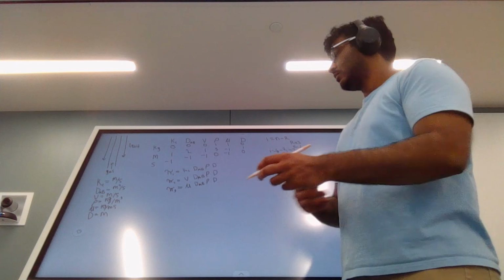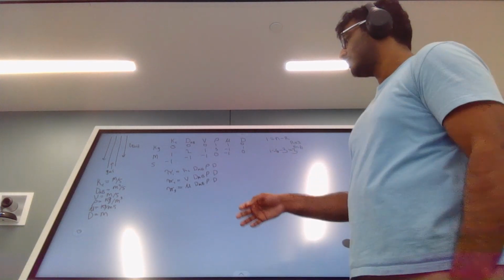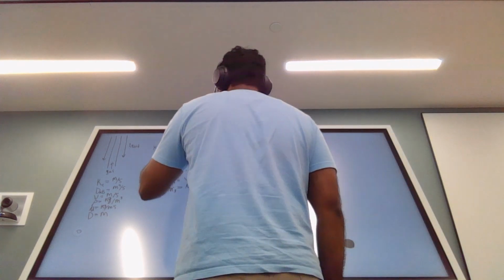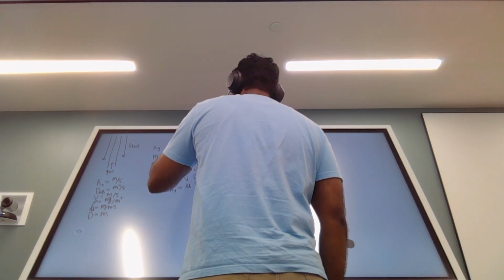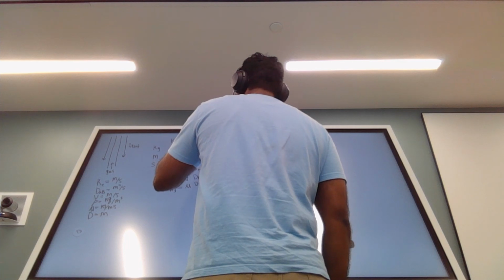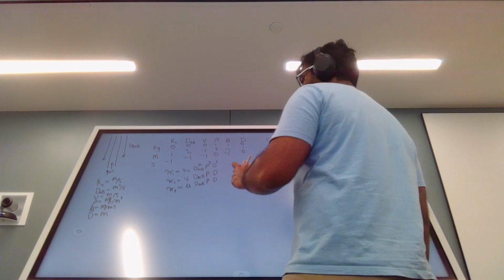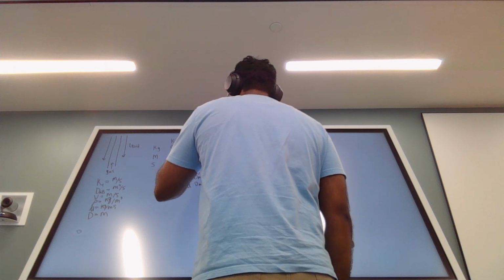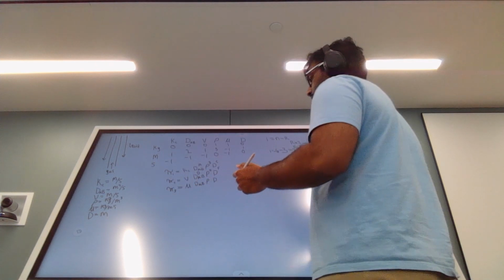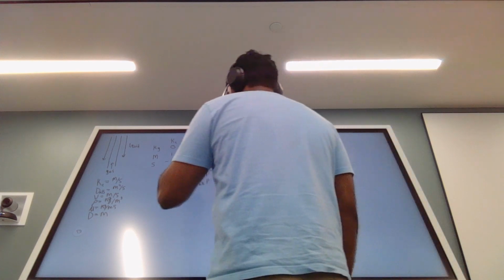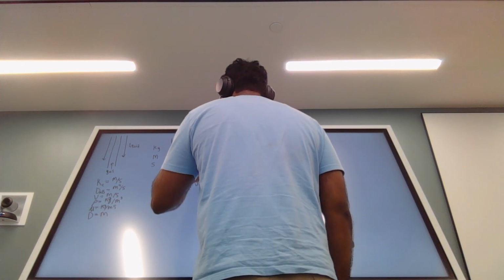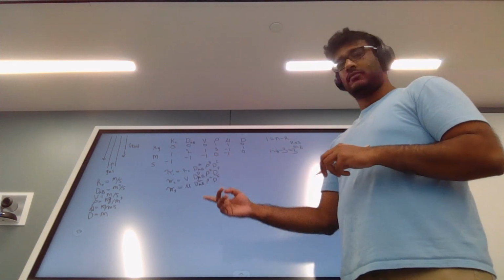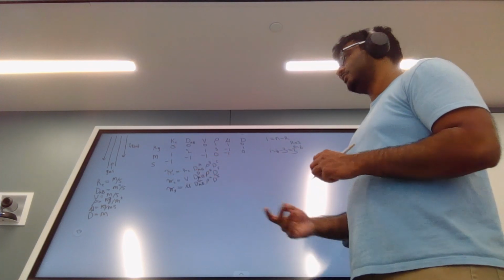All right, so now what we're going to do is assign a power to the variables that are not isolated. So for example, we're going to say DAB raised to the A, density raised to the B, and diameter raised to the C for pi 1. And then it's going to be D, E, F for pi 2. And then for pi 3, it's going to be G, H, and I. So they all have to be different exponents because they're going to be different equations, right?